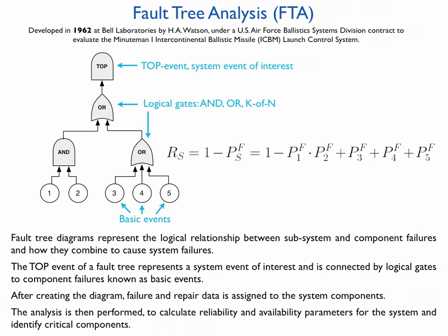And using the same logic, we can produce the Boolean expression for the top level event using these ANDs and ORs. And if we know the probability of failure for these basic events, for these components, we can compute the probability of failure of the entire system using this logic.